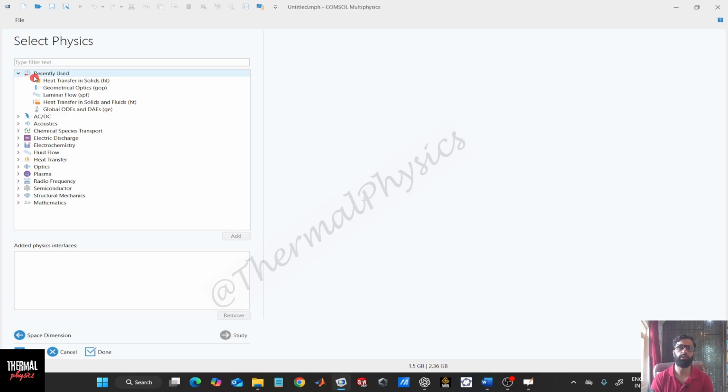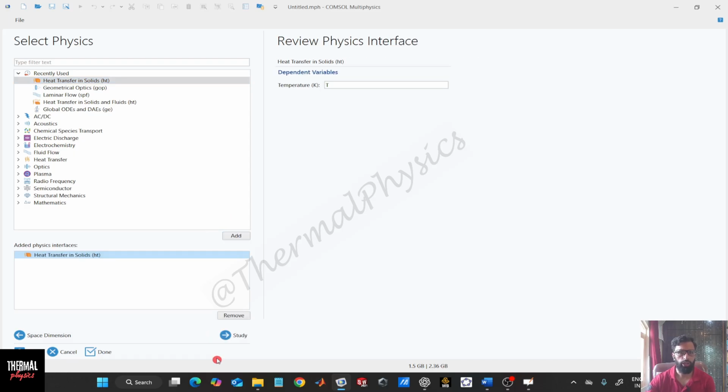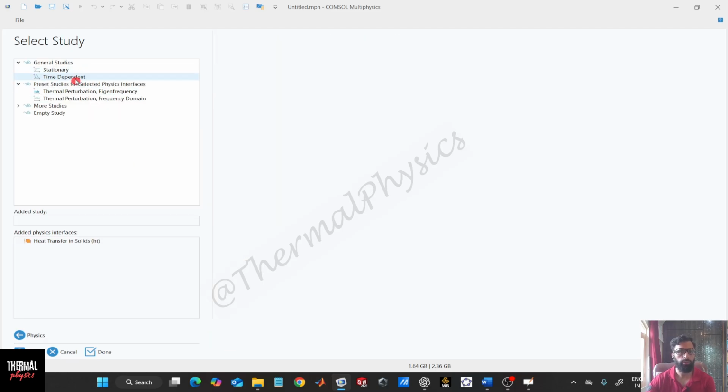So we'll choose a very large value of k, so that there are no temperature gradients inside and our Biot number will be much lesser than 0.1. Our T of t equation does not have k, and our time constant does not have k, so it's independent of k. So we'll choose 3D Heat Transfer in Solids and put a large value of k to make the Biot number much lesser than 1.